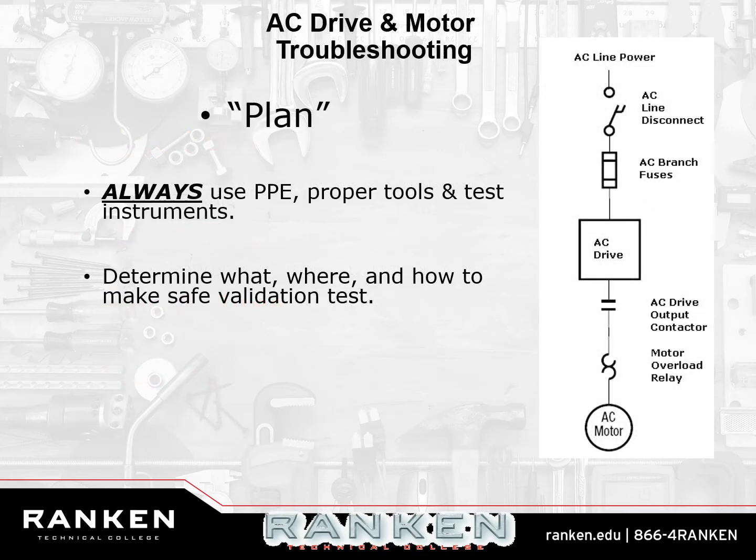So what is the plan? What kind of PPE do I need? Like I said, what kind of tools do I need? What kind of test instrument do I need? And you notice I use the word proper tools. That means if I need a hammer, I bring a damn hammer. It means if I need a screwdriver, I bring several screwdrivers of the right sizes. I don't try to cram my panel screwdriver into a big honking flathead screw and I break my panel screwdriver, or I round out the screw. If I need a Phillips screwdriver, I use a Phillips screwdriver.